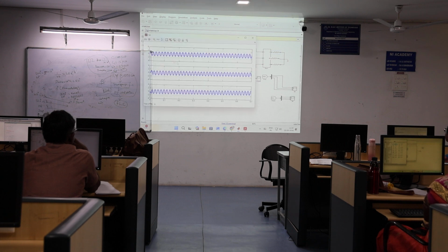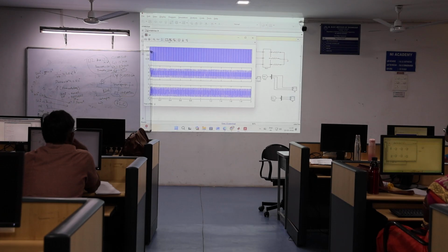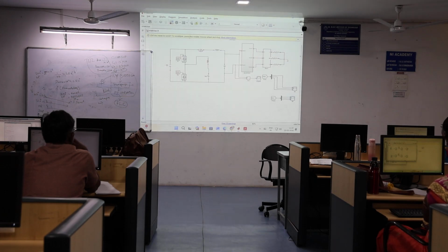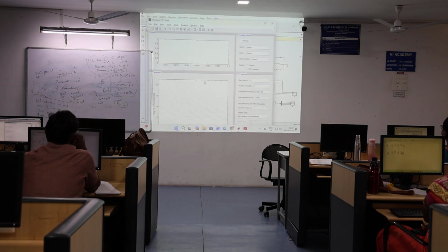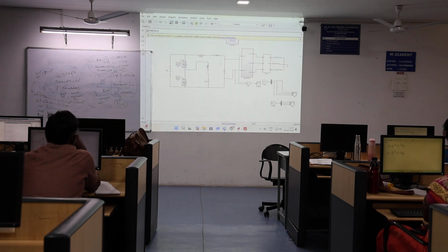So here when I see my THD value, it will be comparatively higher only. To view the THD, you go to the discrete and you have the FFT analysis. You click on that.